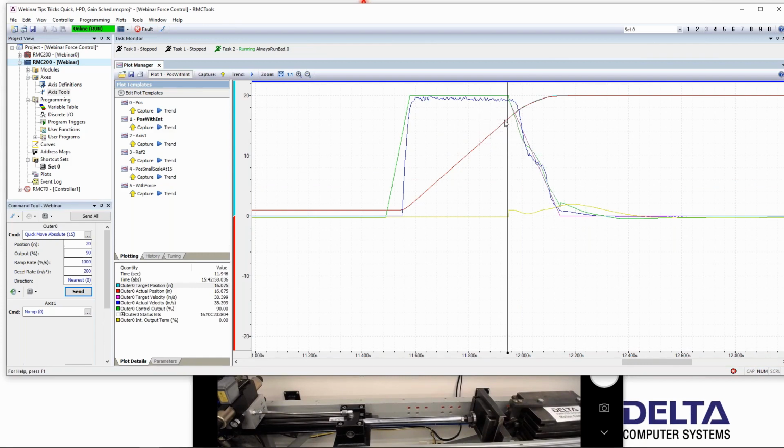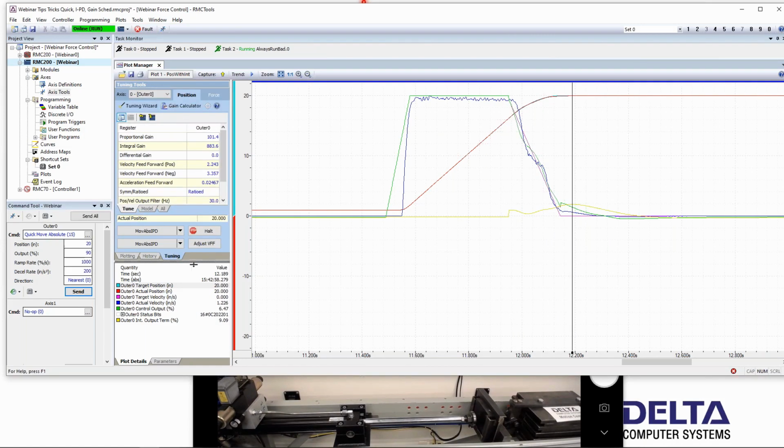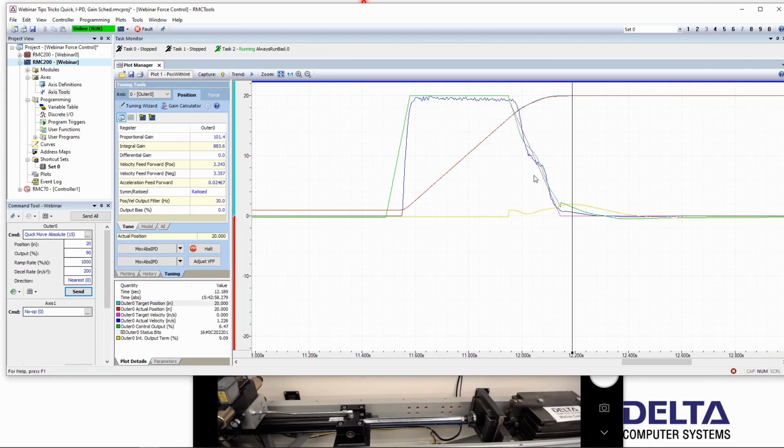I see right here when it switches to closed loop control that I'm getting a little bit of bump in the integral gain, but not so much. And then of course it's non-linear as it's decelerating, so I have some issues with that. But the integral gain is keeping me on the right side of the target, the undershoot, assuming that I can't handle so much overshoot. So I'm getting a little bit of overshoot, but if I need to tune it, all I have to worry about is this section here. Now, I'm not quite sure exactly what I would do to improve this tuning a whole lot.